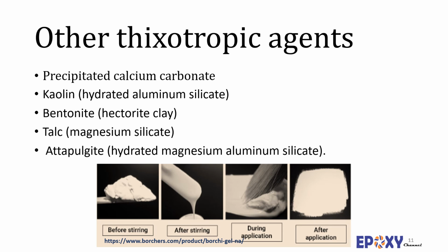Attapulgite particles are easy to disperse, and at 10 to 20 weight% loadings, it can be considered as a partial asbestos replacement in polymeric-based sealants for the construction and automotive industries. Microcellular fillers such as glass and plastic are also used to provide non-sag properties in epoxy systems, with a different mode of operation though. In fact, microcellular fillers drastically reduce the specific gravity of the product.